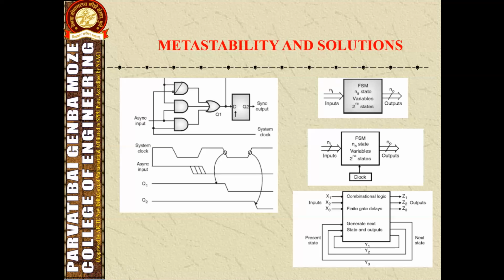In the combinational output logic, the output in the finite state machine is a function of the current state and the primary input. Generally, in a more complex finite state machine, the user wants to derive the outputs from the next state.